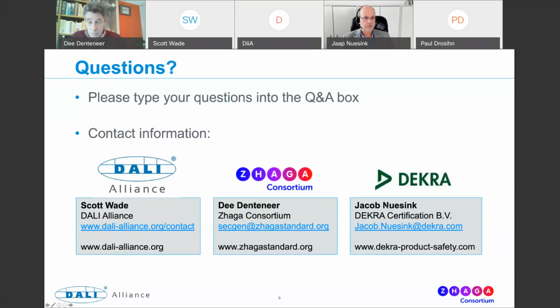Well, maybe so. Control devices also need to implement parts 101 and 103. So it's not just part 351. You need to implement those 3 parts as a minimum. It's optional whether or not the manufacturer builds in sensor technology. For example, one type of control device for outdoor luminaires might just be a time clock, and there's no sensor in there. So that's permitted. We don't disallow this kind of product. But you can also build in light sensors, occupancy sensors, or other types of sensor into those devices, those nodes or control devices. So it's not limited in what you can do.